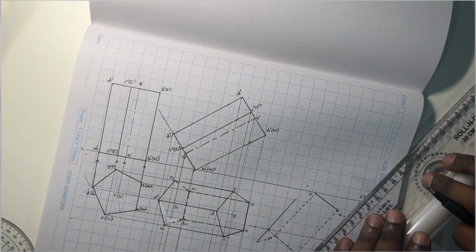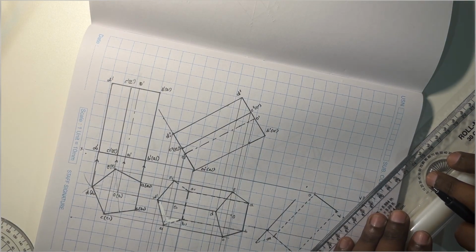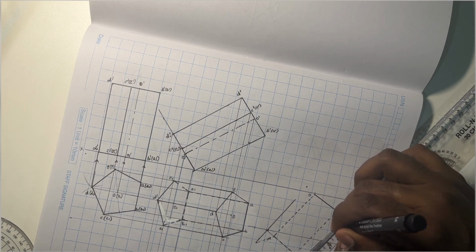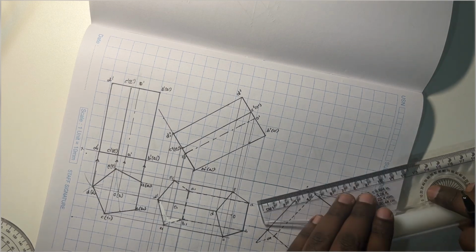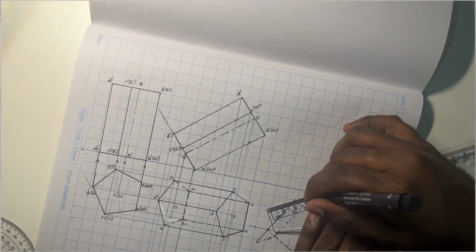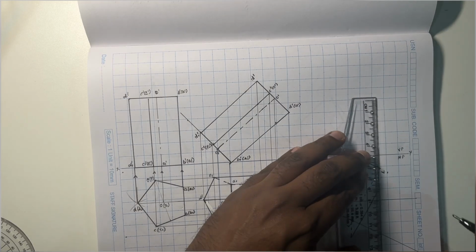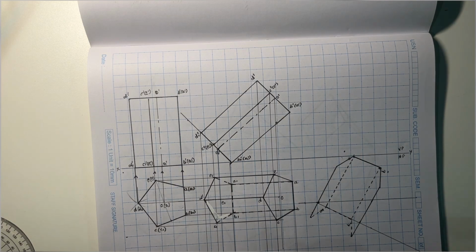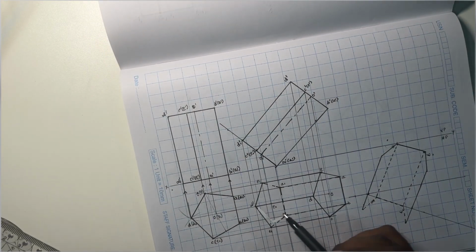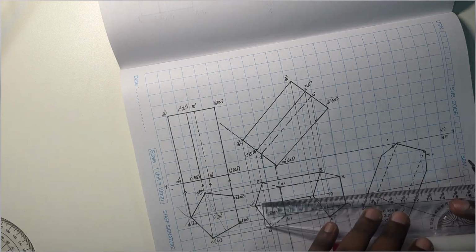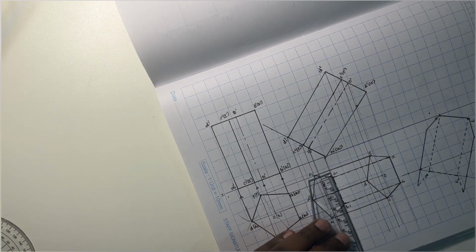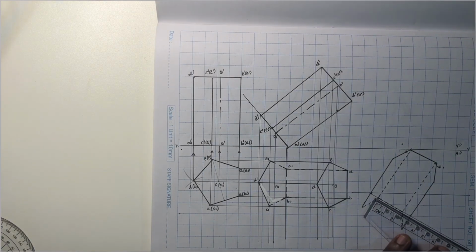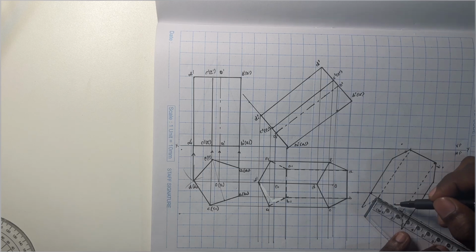So I'm going to transfer that with 90 degrees as the reference point. So now these are the points, that is A1 to E, or A to E, and B to C. So now I need to locate the point D. So D, O1, D and O are all on the same line. See here, A1 to B1 is bisected, and from that midpoint only all these points I'll be getting. So what I'll do is I'll just mark the midpoint of this A1, B1.